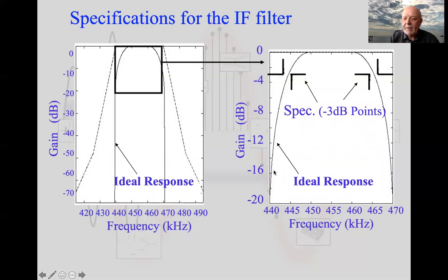So it didn't matter so much here if it wasn't quite the same here, and maybe at the top here it might dip or something slightly at the top here. But the important point was that it goes through these, if you like, gates at the 3 dB points, and that actually then improved the response of the circuit.